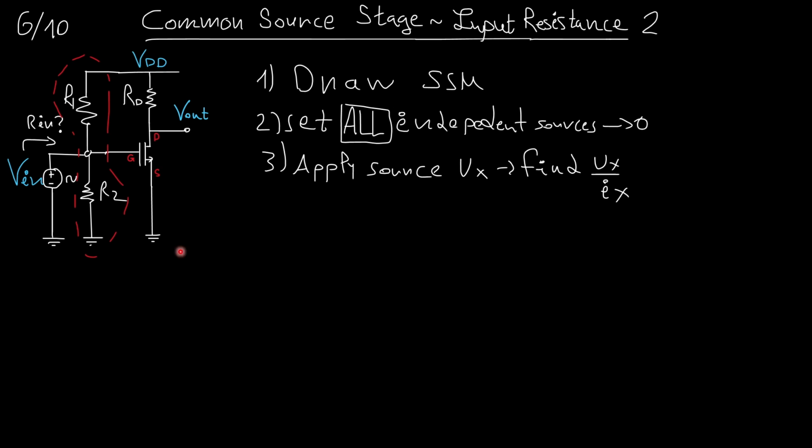All right, now if we don't want too many batteries, and we don't in our circuits, and we still want to bias it properly, then we're going to add a resistance divider between the drain and the ground of two resistances, and we connect the input signal like this.